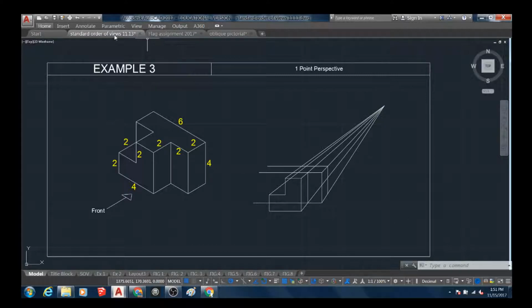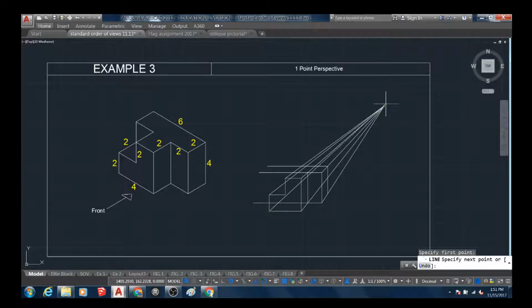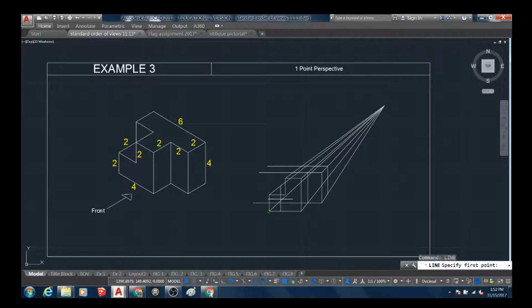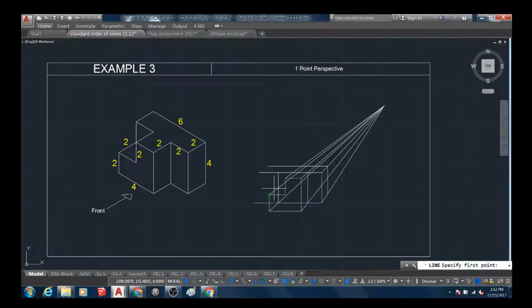Now here's the tricky part. We need to go from this end point to the vanishing point so that this intersection right here, straight up, will give us this front plane. So at this intersection I go straight up here to that intersection. And this intersection that I have right here becomes this line and this line's intersection. Now it's left just to go here.